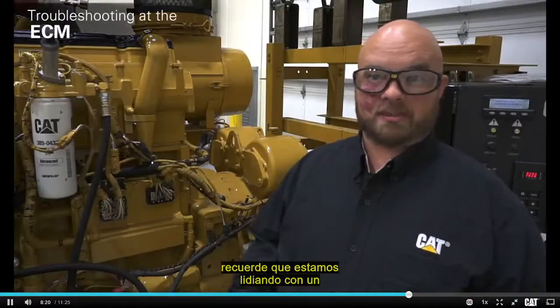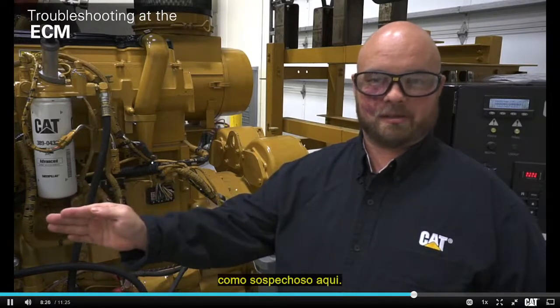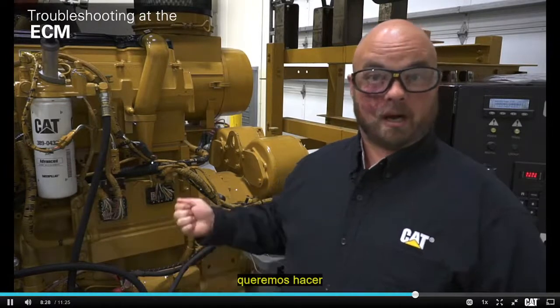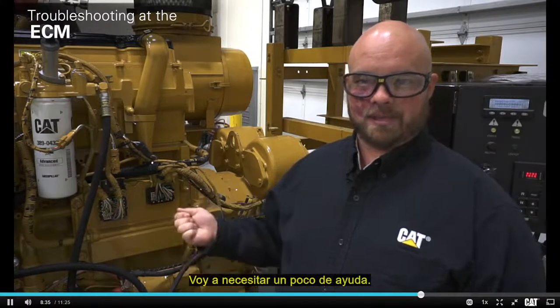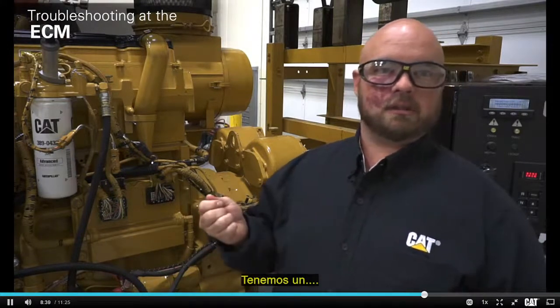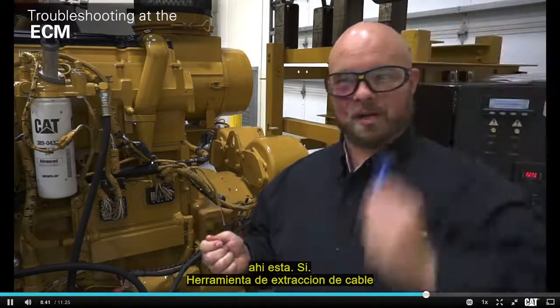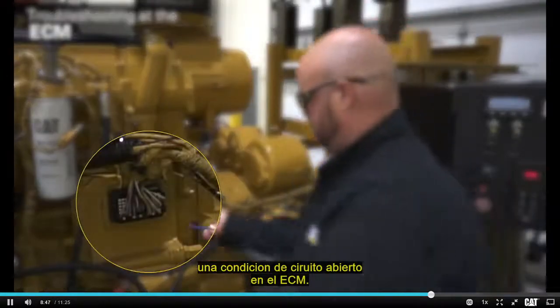So we've identified that. Remember, we're dealing with a -4 voltage below normal code, and we've eliminated the sensor as being a suspect here. So at this point, we want to make that opposite condition again, only this time we do it at the ECM. In order to do that, I'm going to need a little bit of help. Let's see, do we have... oh, there it is. Yes, wire removal tool. Thanks, assistant. So at this point, we're going to create an open circuit condition at the ECM.